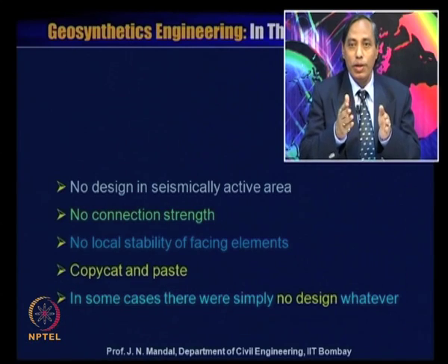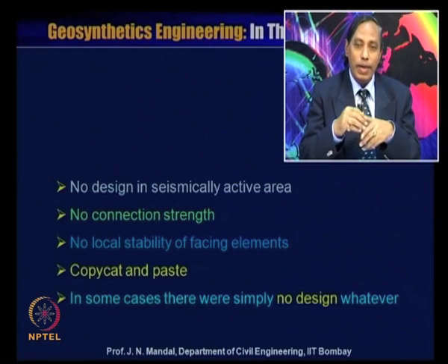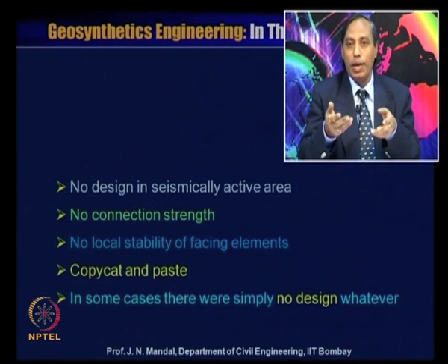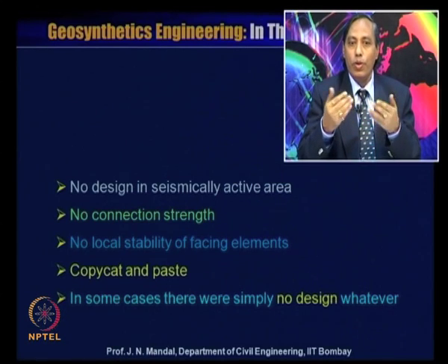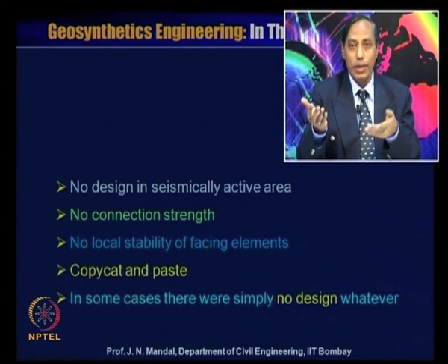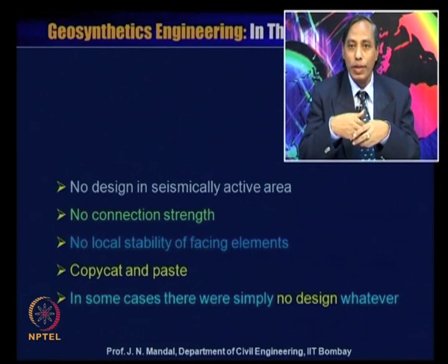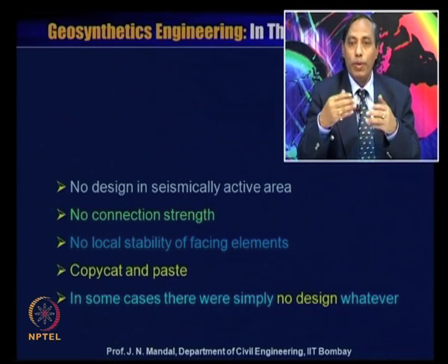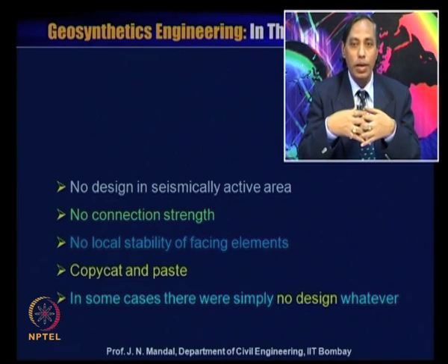And also, each and every facing element is required for local stability. Sometimes you can see there is no local stability of the facing element. In many cases, designers, whether professional or non-professional, just copy and paste the design, which is 30% cheaper than what you would get from other sources. But they do not know what the problem will be in future, or when a failure may occur due to this kind of design. So, one has to be very cautious about that design.